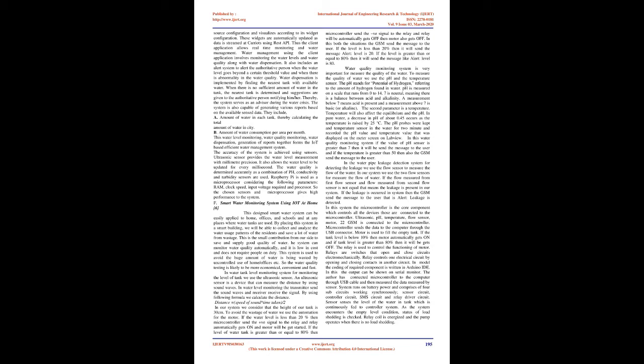In both the situations the GSM sends a message to the user. If the level is less than 20%, then it will send the message, alert, level is 20. If the level is greater than or equal to 80%, then it will send a message like, alert, level is 80.